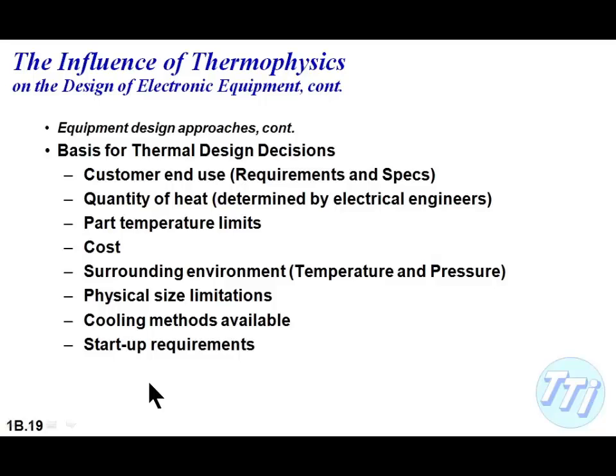Certainly designing a device to go in a submarine, your cooling resources are much more limited than, say, a surface ship. And so knowing your surrounding environment, where your heat sinks are, where you can dump your heat to, and what modes you can use to do that, play a big role.